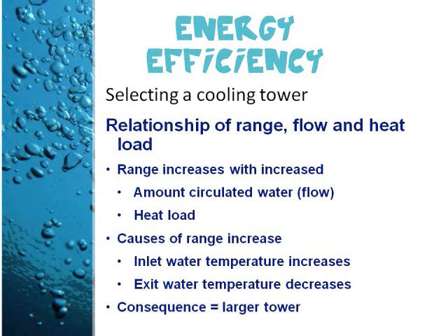In this case, it is economical to invest in removing the additional heat. The exit water temperature is decreased, and the hot water temperature at the inlet remains the same. In this case, the tower size would have to be increased considerably because the approach is also reduced, and this is not always economical.